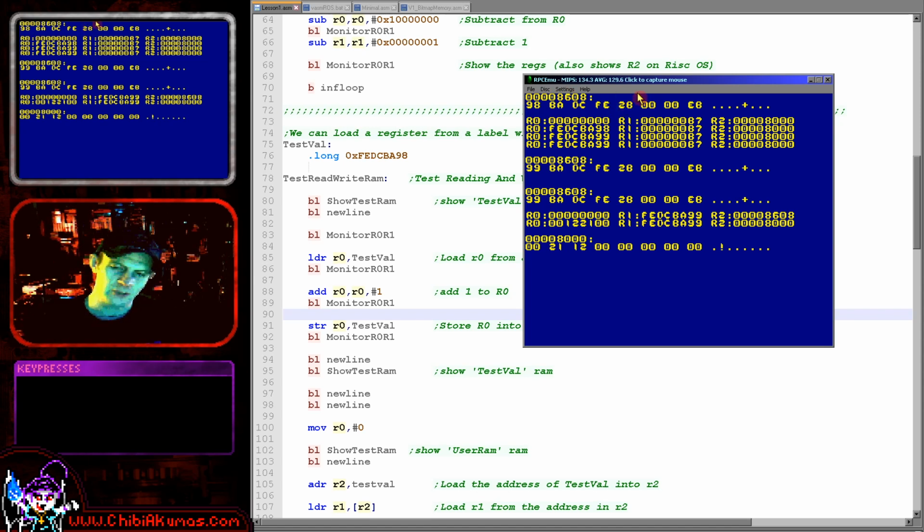Now that's probably not much of a surprise to you if you've done assembly before. This is something known as little endian, where the lowest byte values come first and the highest byte value comes last. So 98BADCFE here is just this reversed, because that's the way we store things in memory. Now with the ARM processor, that's sort of optional. In theory the processor can work in either mode, but in practice I believe it's basically always little endian. So that's what we will be working with.